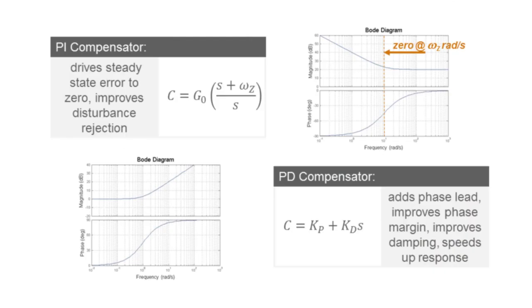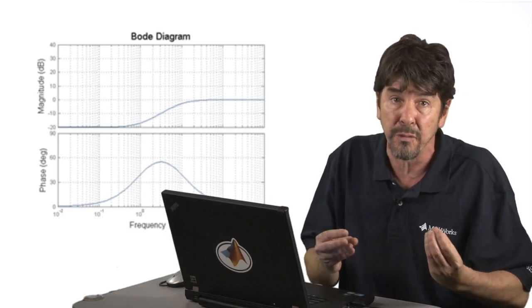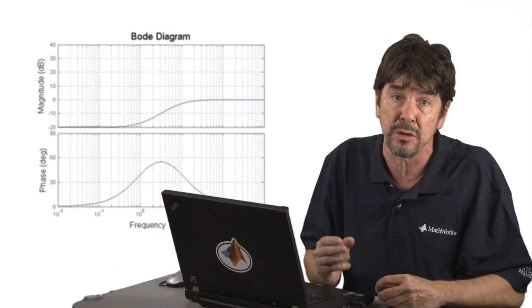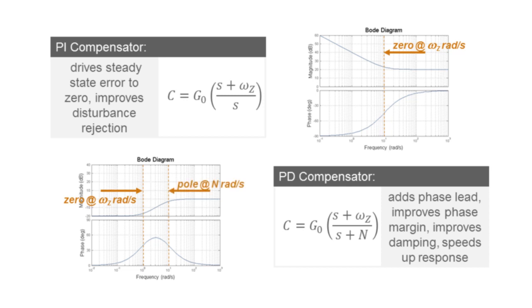So in practice, you will always use what is called a filter differentiator. In essence, a filter differentiator is a pure differentiator and a pole placed at a frequency where we don't want to be differentiating anymore. Once again, as in the PI controller case, to find the frequency response, we cannot just use superposition because of that sum. So after taking a common denominator, s plus n in this case, and factoring the Kp and Kd terms, you can see that this structure, a PD controller with a filter derivative, is essentially the same as a lead compensator.